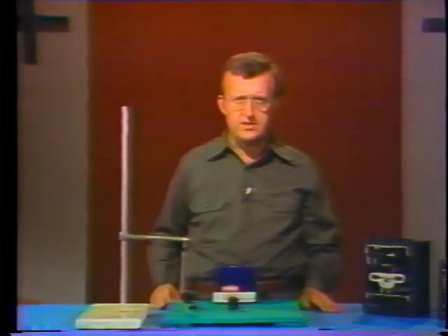A third type of relay, called a power relay, uses relatively small amounts of electrical power to control much larger amounts of electrical power. Power relays are commonly found in motor controllers, where turning a small switch or pushing a button can start a large motor. The use of power relays is often a matter of convenience and economy. Power relays save space and weight because they allow the use of small switches and lightweight control wires at remote locations. These switches let an operator control large amounts of power at other locations without requiring heavy power cables past the point where they're actually needed.